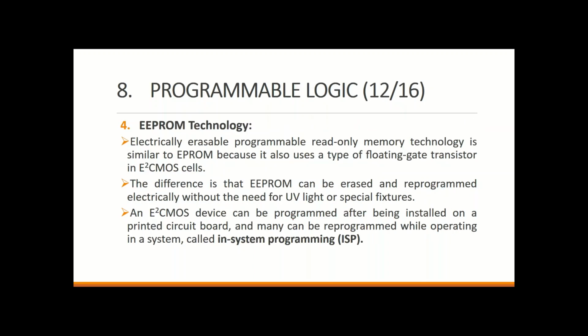We have the electrically erasable programmable read-only memory technology, and this one allows you to program it usually in system programming or even by some circuit board technology. It's possible for you as a programmer to do it without going to specialized laboratories to do that for you. So that EEPROM, sometimes they write it E squared PROM or E squared CMOS. CMOS is also one type of metal oxide semiconductor, the complementary type. You don't have to worry about what it is. It uses the same technology, the floating gate transistor.